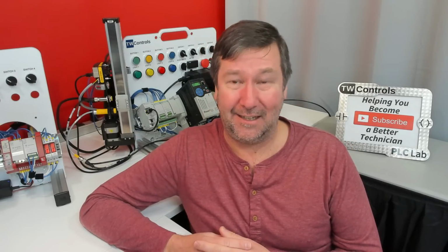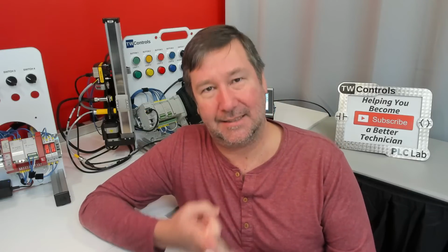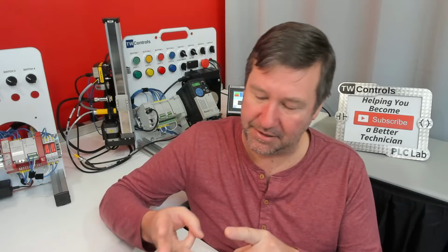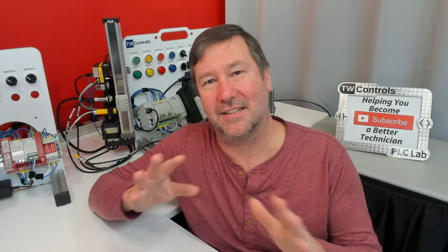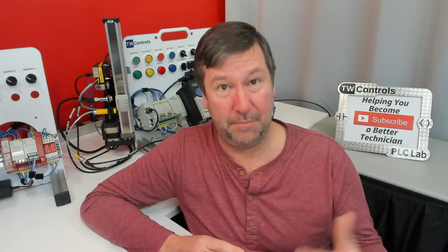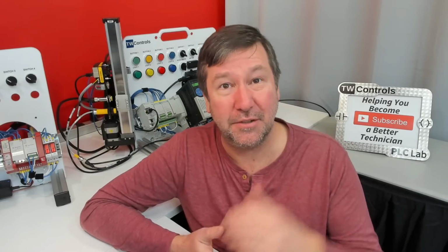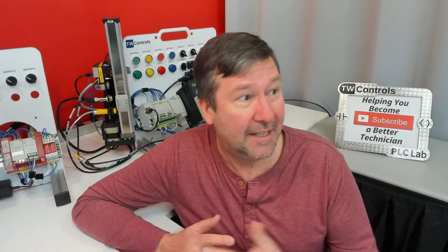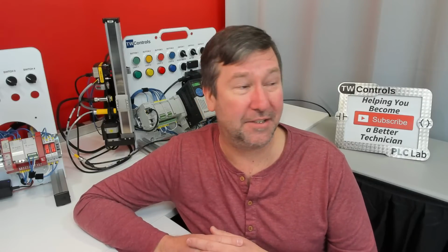Now his point in the end was very valid. He's like, Rockwell has a sequence instruction. Siemens has a different sequence instruction. All of them have something different. If you make it the basic compare, are we on step one? Are we on step two? If you use those basic instructions that all of them universally use, then my folks can troubleshoot all these machines.